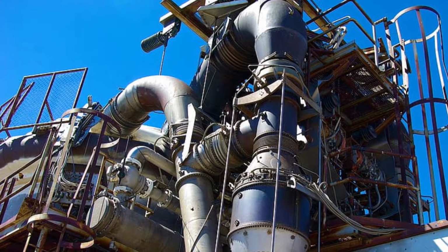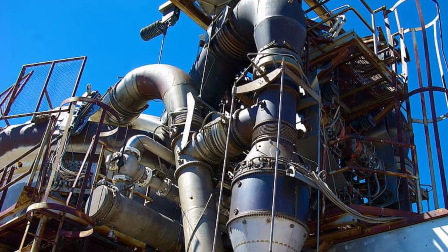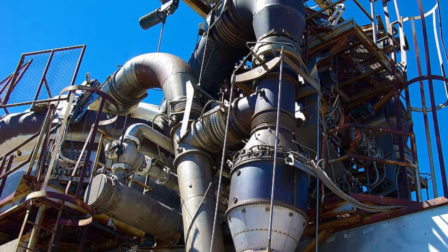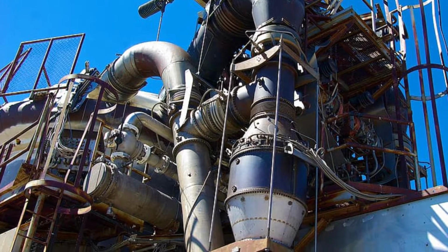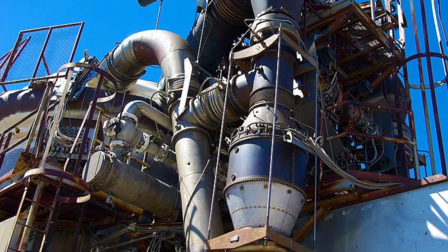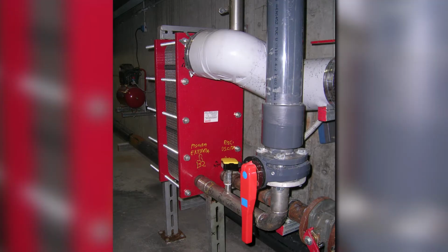There are two common recommendations given by the IAC related to waste heat recovery. The first is to recover waste heat from equipment in the form of liquid, steam, and radiant heat. One good example of this is recovering heat from a boiler blowdown. In this case, heat from the blowdown water will preheat the feed water and reduce the amount of thermal energy required to heat the feed water once it enters the boiler.